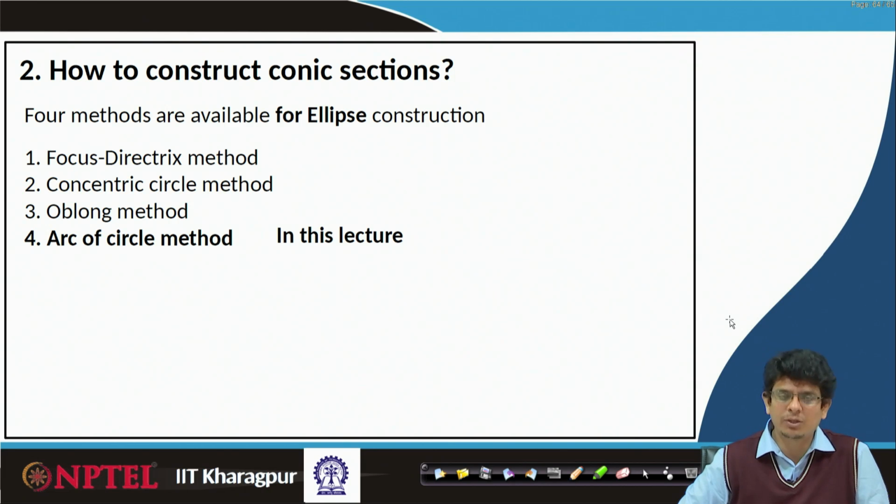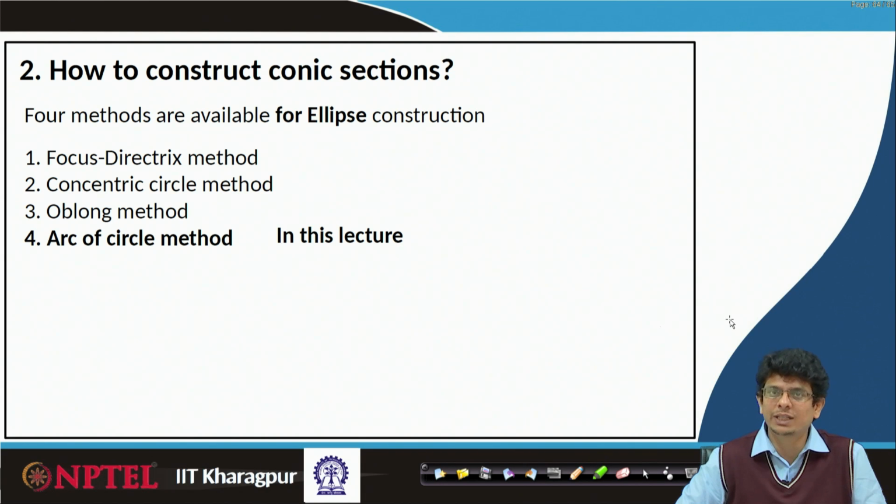In the arc of circle method, we have seen the major axis is given, and the distance between foci is given. So, using a principle, for any point where we would like to construct this ellipse, A1 plus B1 will always be the major axis length. Using that principle, and with radius from F1, F2 the foci centers, make many arcs, intersect them and construct an ellipse.